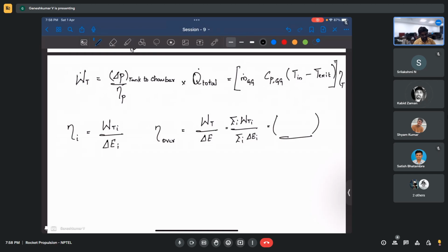So in this particular question, does combined efficiency mean that 0.8 is the efficiency for the pump as well as 0.8 is the efficiency for the turbine? You no need to do that, that's what I'm trying to say. In this analysis, there's going to be only one turbine and one or two pumps, but the two pumps act on the same pressure difference, so you can see it as one pump with the same pressure difference.